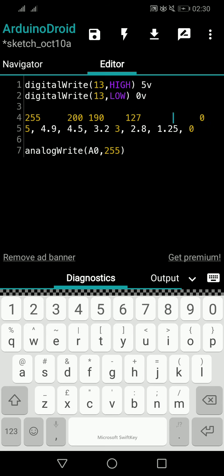You can have any values. So that value you have to pass here. Okay, that's understandable. That's very clear, right? So actually this whole 5 volts you are going to divide between 0 to 255. Even then you can find out what is the voltage value of this one unit, that goes up to 255. So if you divide 5 by 255, you can even see what is the voltage value of 1 unit. And if you give 1, then you will understand what is the exact voltage value given to the particular pin.